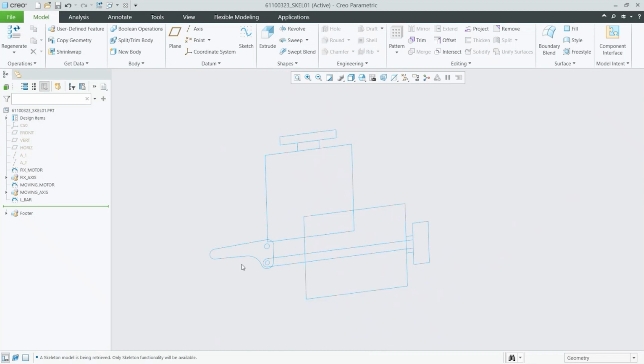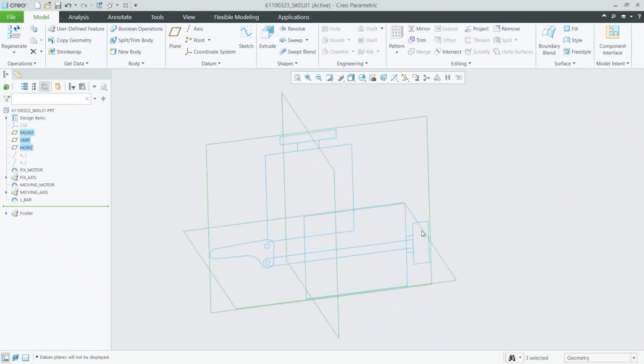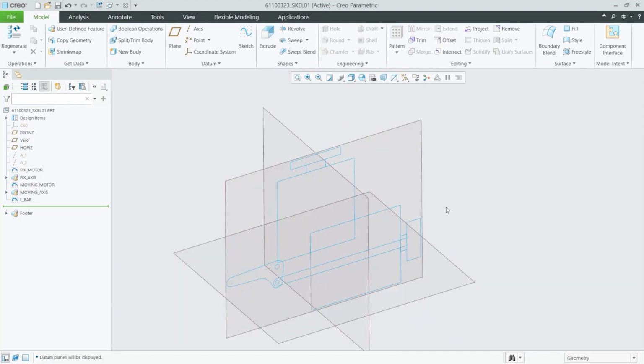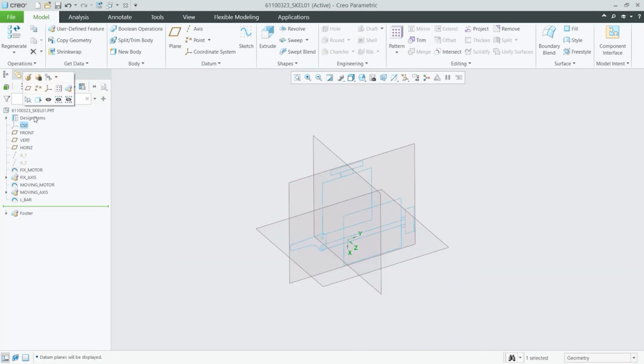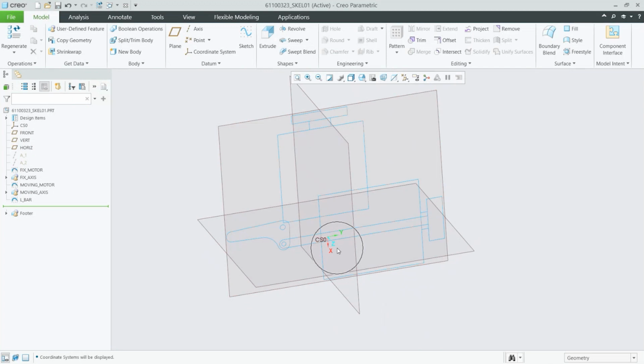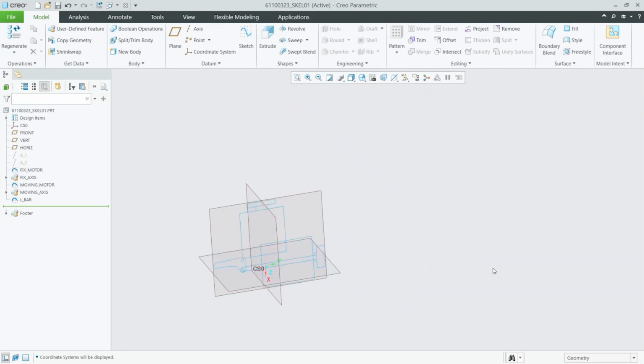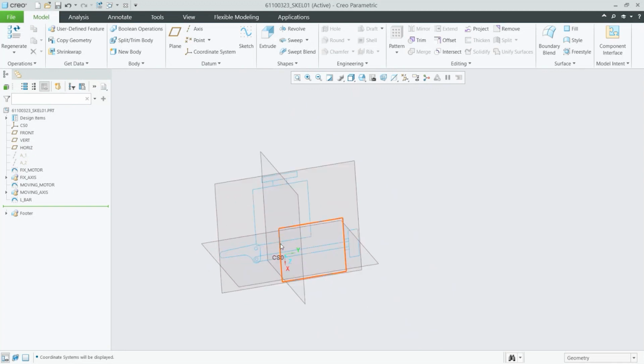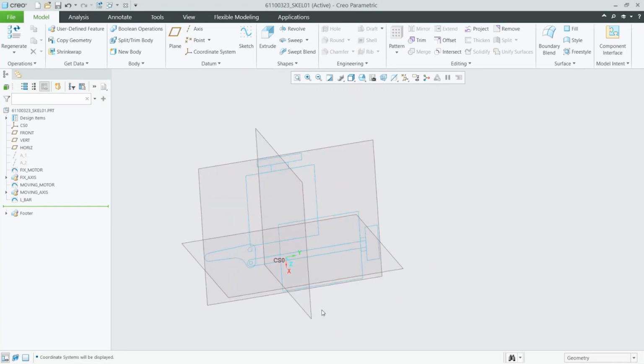Okay, so once you do all this information in a skeleton model, in the actual skeleton model, you may have a lot of curves like this. You may have a lot of datum planes. You may have a lot of coordinate systems. For an engine, for an automation company, they may have a lot of coordinate systems for the location of the module. So you may have a lot of information in the skeleton model. So how can we effectively inform the downstream what information you need to copy?